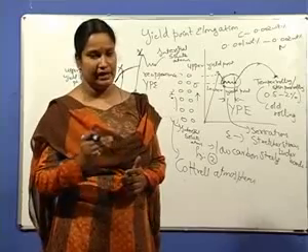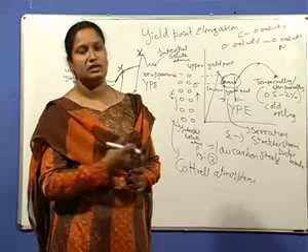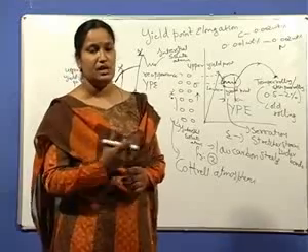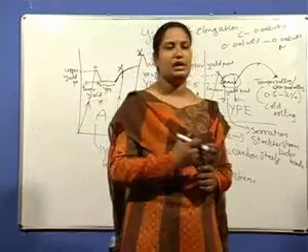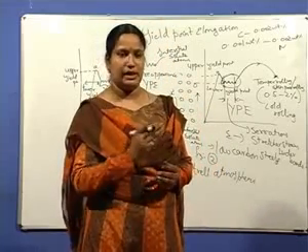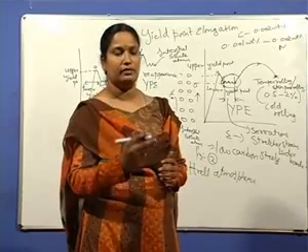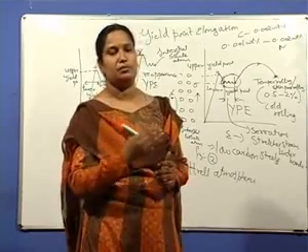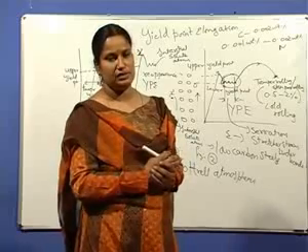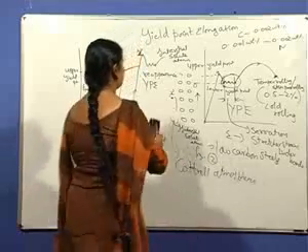It occurs at slightly higher temperatures, because at slightly higher temperatures the carbon and nitrogen solute atoms diffuse rapidly and are more active, so they quickly form these atmospheres. They form fine serrations in the stress strain curve.